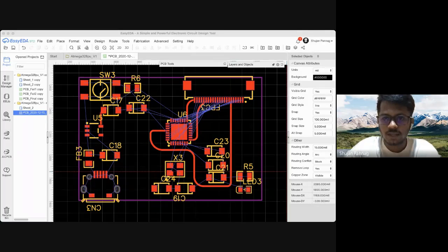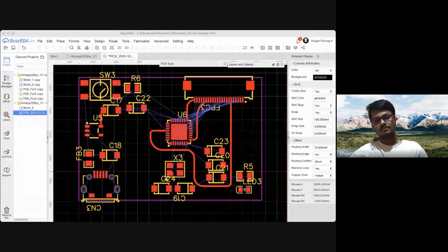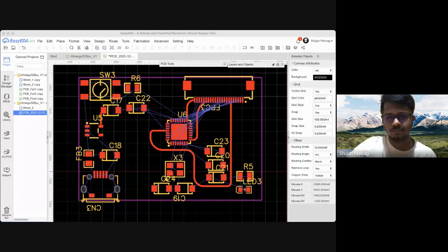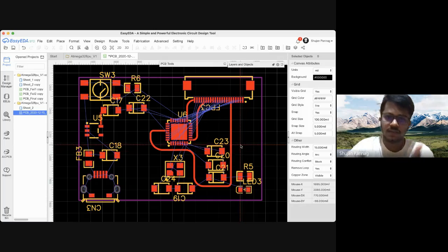Yes, I know. Yeah, that's the right answer. Yes, we use vias. But why? Anyone? I just spoke about that in our issues. I showed it in the PPT. Loop acts like an inductor. Yeah. So there are two things that are happening here.